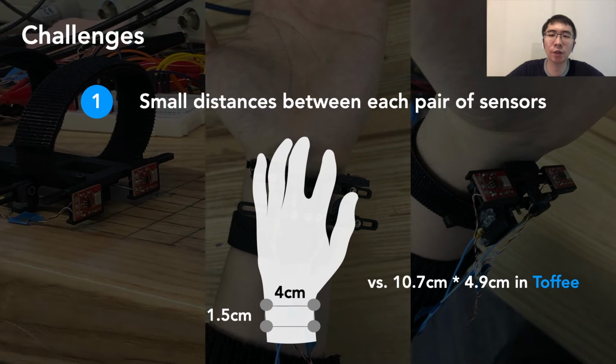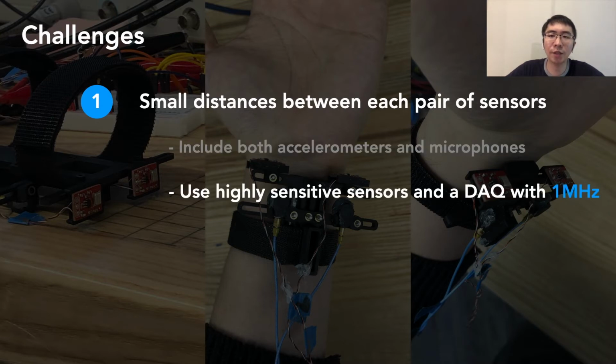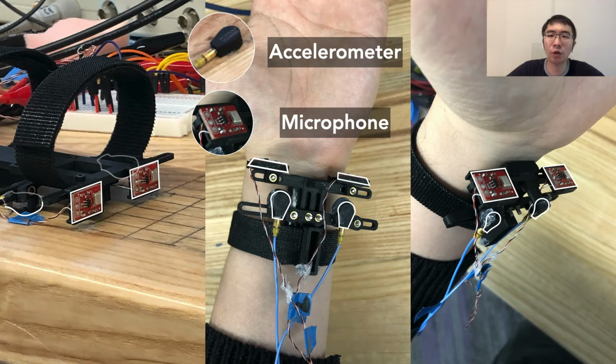First is the small distances between each pair of the sensors, which makes it hard to estimate the TDOA difference. To mitigate this issue, we first included both accelerometers and microphones in our wristband. Since the propagation speeds in the surface and air are different, this could actually add extra time difference and improve the sensing resolution. Please refer to our paper for a detailed explanation. We also selected highly sensitive accelerometers and microphones in our wristband prototype and leverage a DAC that can support as high as 1 MHz sampling rate. Here's our wristband prototype. 2 accelerometers and 2 microphones are situated on the bottom of the wrist with a mechanical structure.